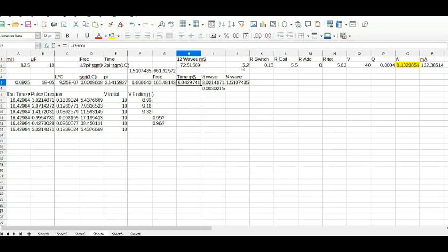Now over here we're dealing with the resistance in the system. This is the resistance in the coil. It was just measured on a cheaper meter, so I trust this one. This is the resistance in our switch, 130 milliohms. For a while I was adding resistors just to have fun and look at how quickly it damped out, and there'll be another use for this later on. So the total resistance is this plus this.